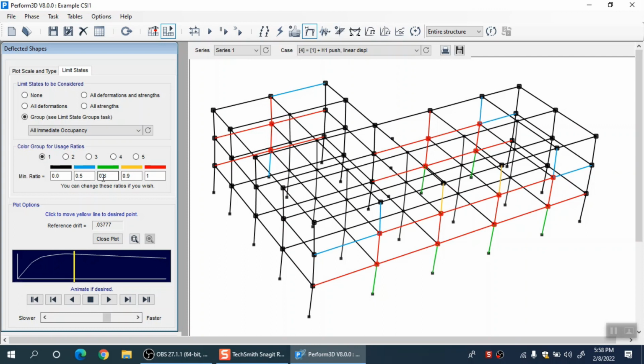There are separate methods for that. This is a big question actually in pushover analysis, how to calculate the target displacement. Target displacement means the roof displacement value which the future earthquake is going to produce in your structure. So, if you can get that number approximately from some other analysis procedure or methodology, you can push your building up till that displacement and all those results are now your seismic results, right.